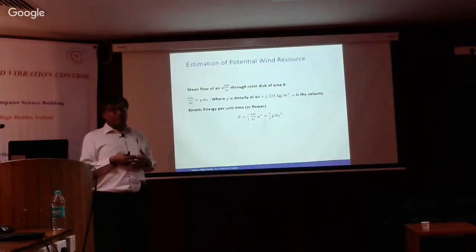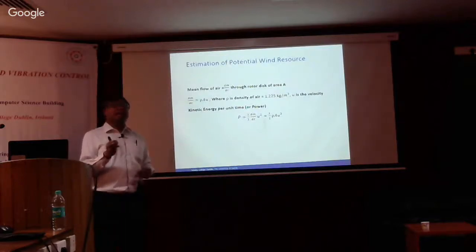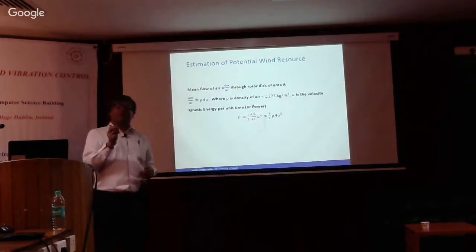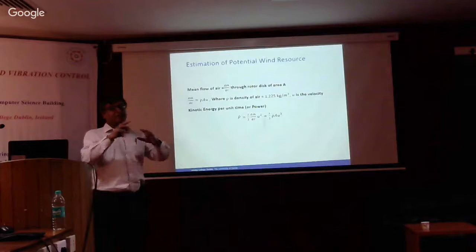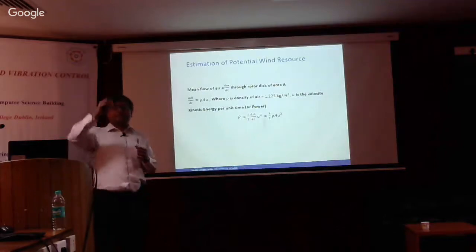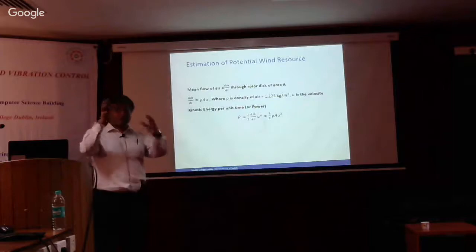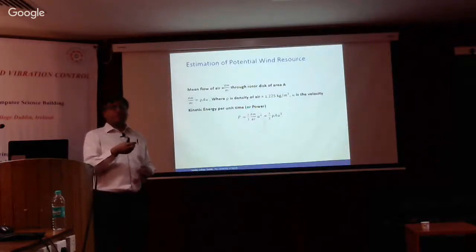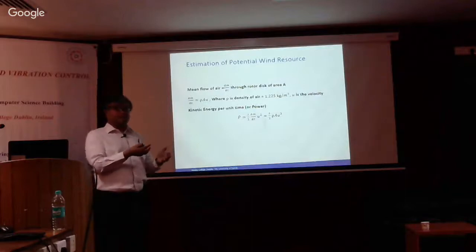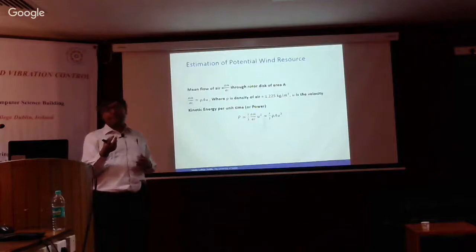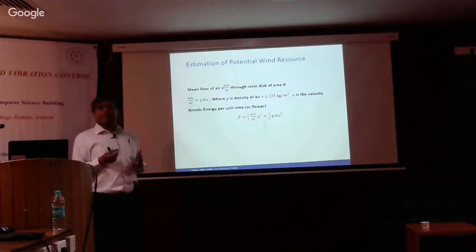And in fact, in a very recent work, which we haven't published yet but have sent to the Journal of Fluid Mechanics, JFM, we have very recently shown that you can have sub-atmospheric pressure, which is counterintuitive. Because in a body of fluid, normally you expect that pressure increases as you go inside the fluid, because the weight of the fluid is active. But we found that in a case like this, you might actually also get negative pressure, meaning sub-atmospheric pressure. So this is something that is not very well understood.